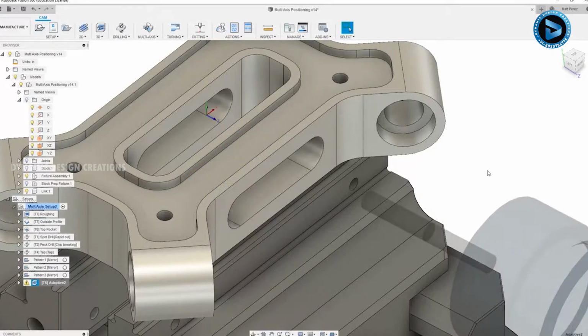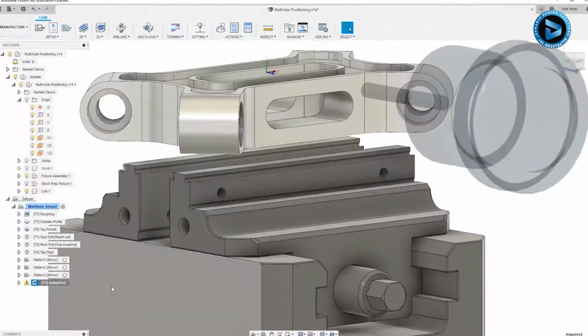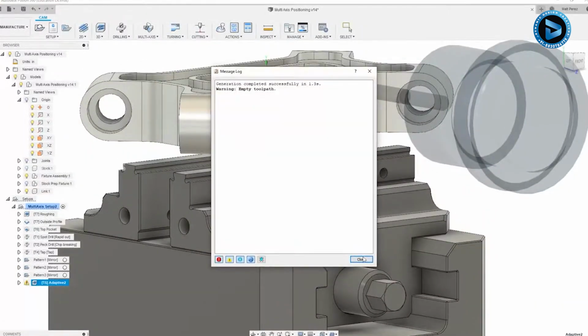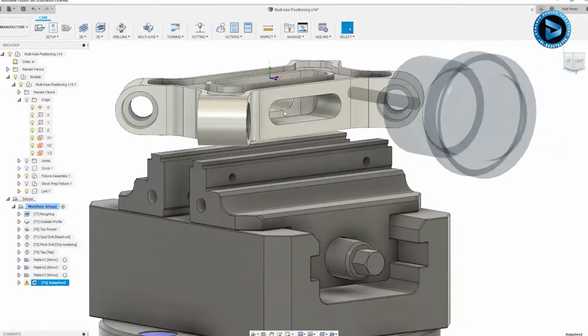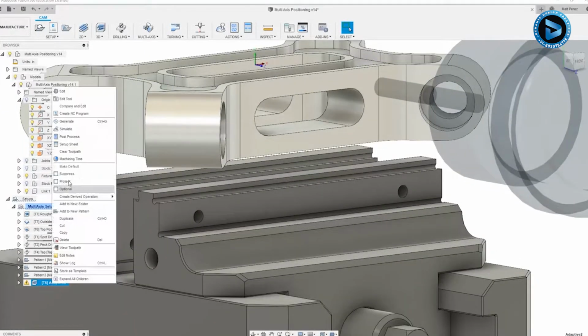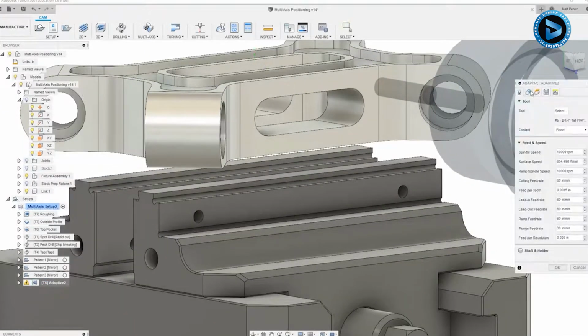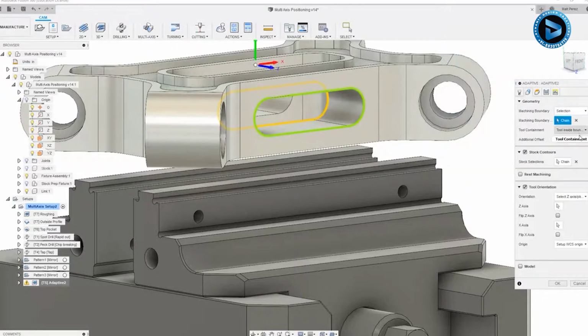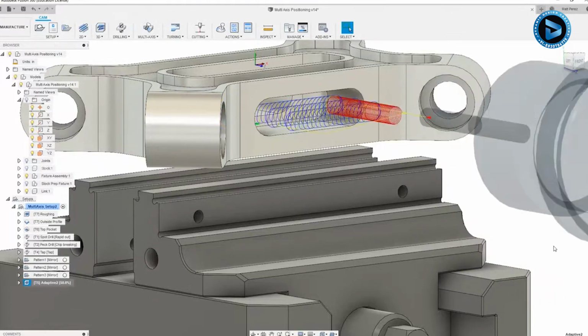Sometimes when we're working with these toolpaths and we're working in multi-axis, we have to just explore some of the options. In this case, we have a warning. It's telling us that it just really can't generate this toolpath, which means that one of my settings is likely off. So in the geometry section, I'm going to take the containment boundary offset down to 0 because the offset is likely going to push that inward rather than keeping it outside. So if we want to make the boundary a little bit bigger, we have to use a negative value.